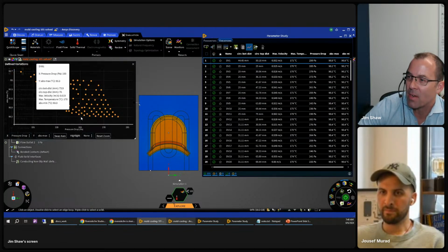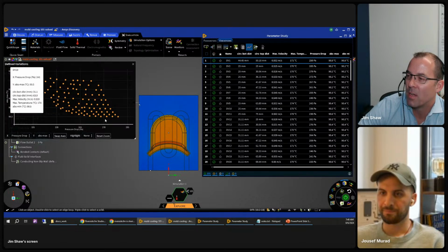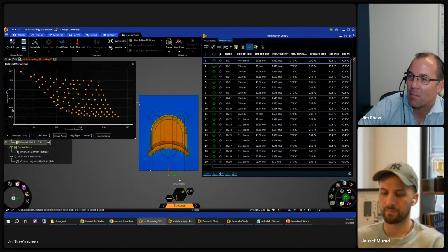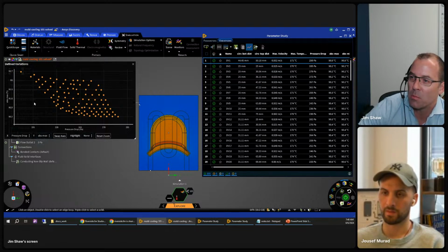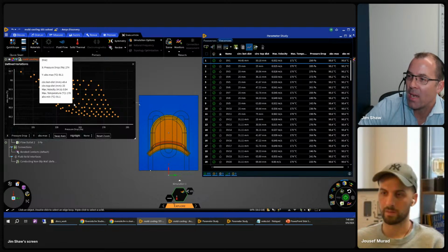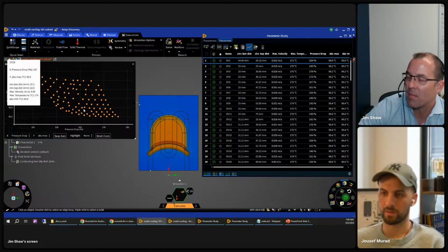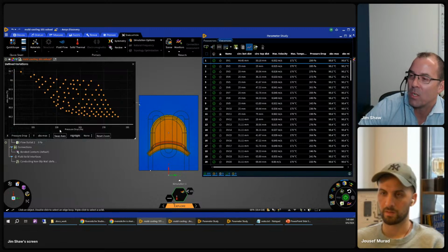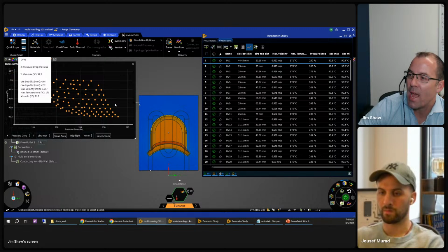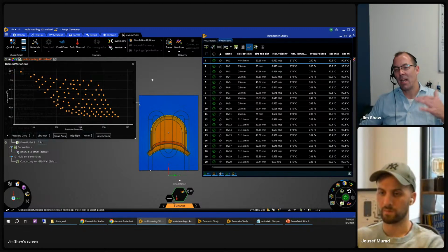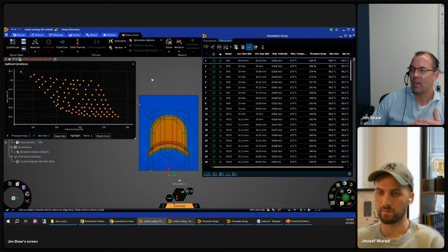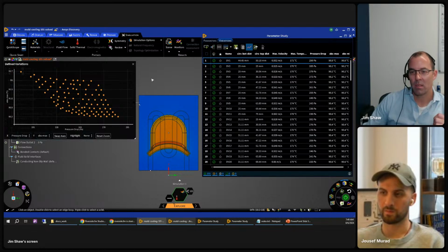But what I've got is my front of optimization. I've got maybe my limit on what I want this mold temperature to be. Let's say I want it to be below 91, which would be somewhere right in here. Now, any combination, you can see I've probably got a few dozen design iterations. Now I want to, again, find which one's the minimum pressure drop. So now this is a data set that as a designer, an analyst, or whatever you want to call yourself, you bring to management.